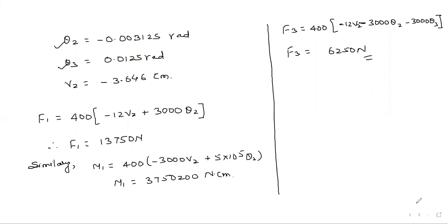Yes, they can ask for the shear force diagram also. The shear force diagram is nothing; already we have calculated F1, F2 and F3. These are shear forces only, right? So you can draw this. This is your node number 1, this is your node number 2, this is your node number 3. So F1 value is 13750. We can write here 13750.